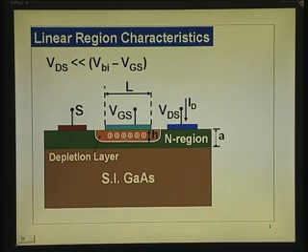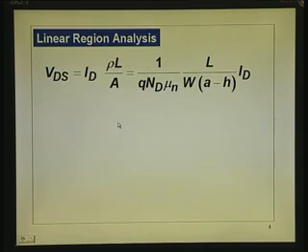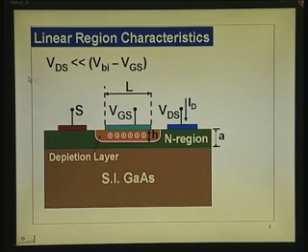These symbols should be clear to you: h, A, ID, VDS, etc., and L is the channel length, depth is W. Now, you see that we have rewritten the equation I wrote initially. VDS, Ohm's law. I say linear region because that is the region where VDS is very small compared to that. When we say linear, the ID-VD characteristic will be linear.